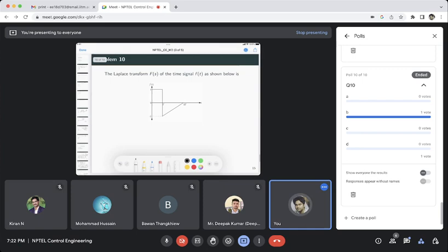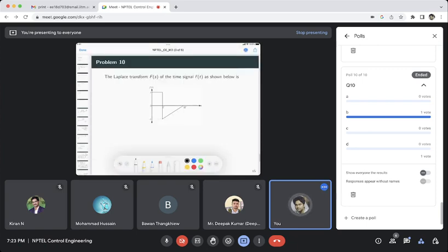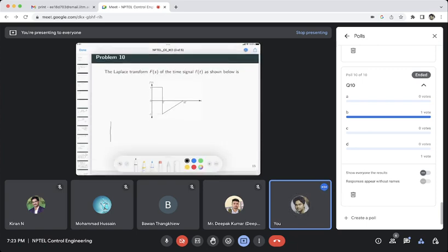So first write this given signal as a sum of simple functions, step function and ramp function, and see whether we can write it. Let's analyze this signal. At 0 we have a step function of height 2, so we have 2 times u(t). But we see that at time capital T, the function is not like this. So what function do we have to add at T to make it minus 2?